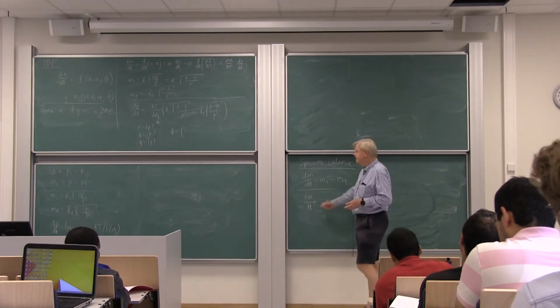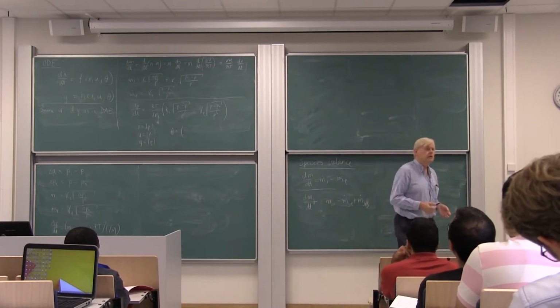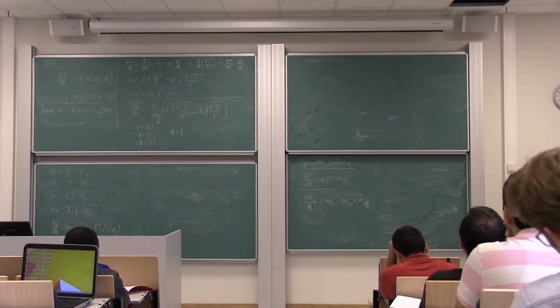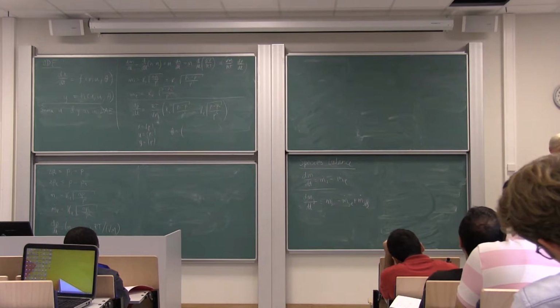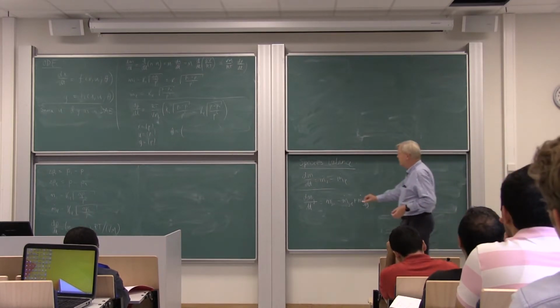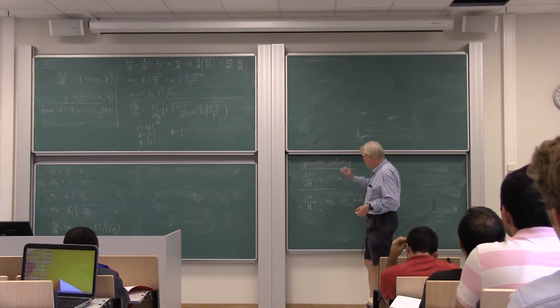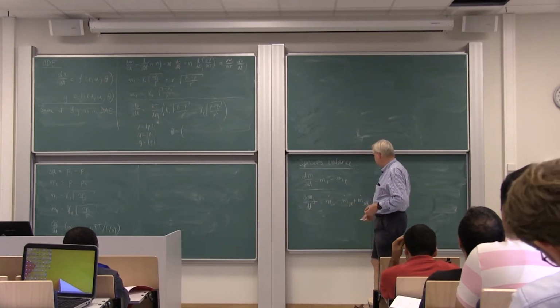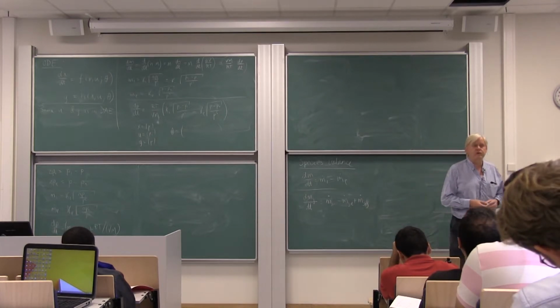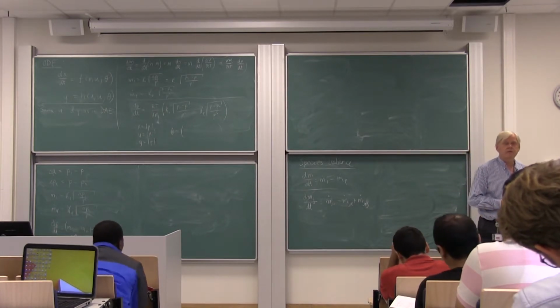The mass of species j, we could have a large number of species, but the mass of species j in the system is equal to the mass flow of species j into the system minus the mass flow of species j out from the system plus possible generation of the species.